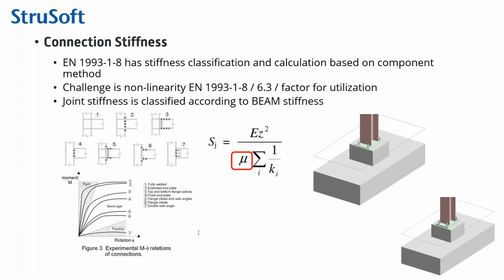The beam will continue to the center of gravity of all the bolts, and there you do your connection to the columns. And with the eccentricity, we will model the situation where the bolts have slipped or they are not pre-tensioned correctly. So that is what we want to model there. So from the bolt group center line to the center line of the column is a good choice for the eccentricity. Okay, we continue.